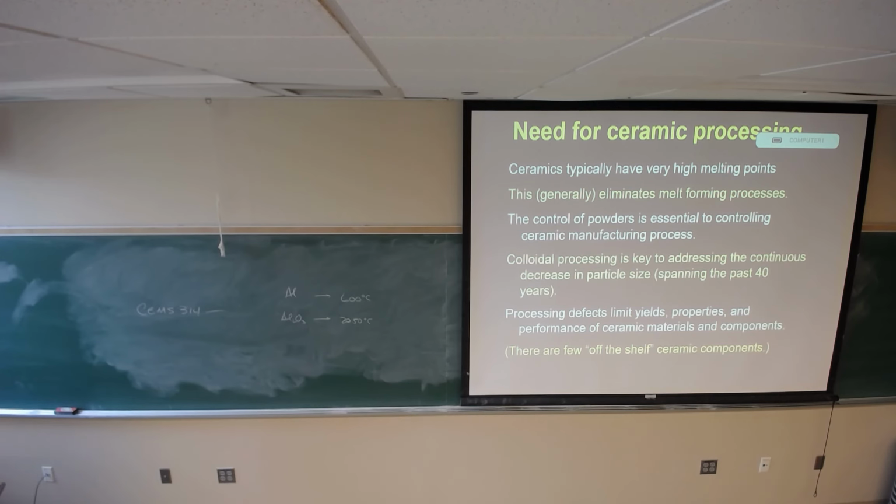Ceramics, by and large, metals, everybody melts them, pours them in an ingot, right? Because of ductile behavior, they'll roll them into shapes, hot rolling, cold rolling, whatever, and you get sheet steel, you get wire, you get I-beams, whatever, right? We can't do that with ceramics. We don't start with raw material melted, form it into something. There are only two industries that do that. In the ceramic world, glass is one, of course, which is sort of pushing the boundaries. We still consider them ceramic, but we're talking about glass forming processes, very viscous fluid. The other is fused cast refractories.